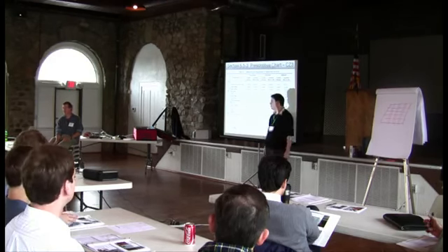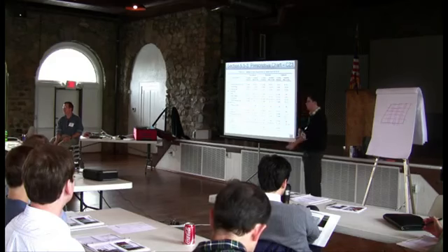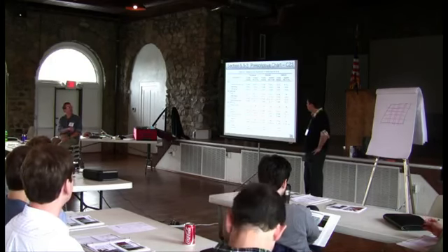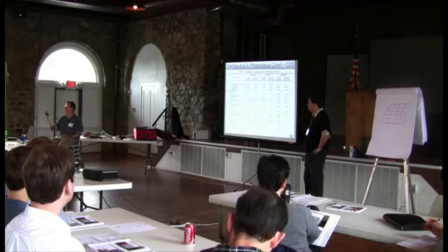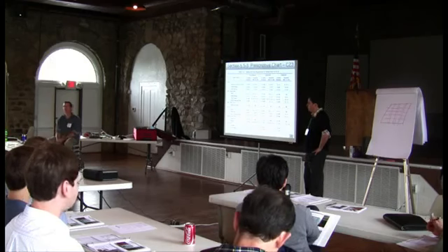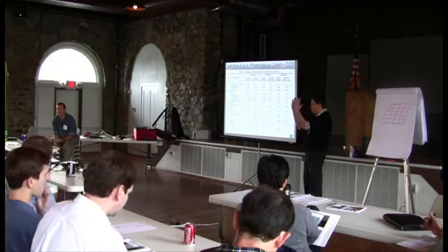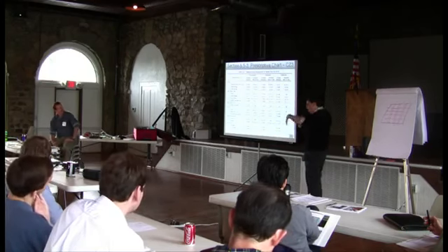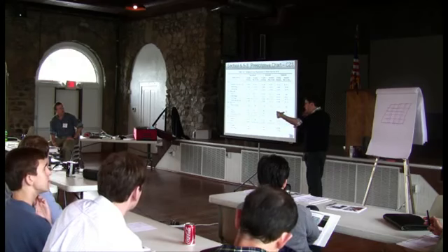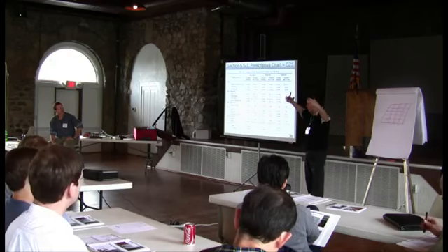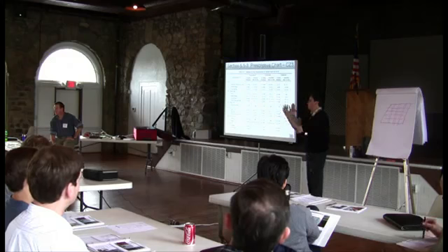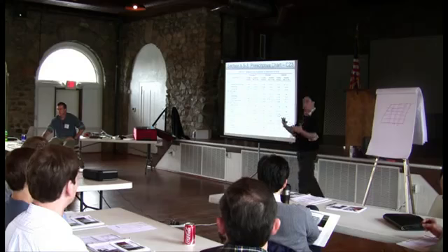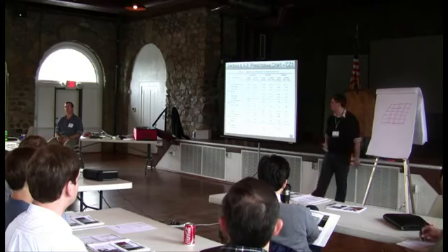Does that make sense, what Brandon just said? And that's an R13, and the other value is the sheathing. Correct. Yeah, the R3.8 is the insulated sheathing. It says continuous insulation is what the CI stands for, right? So you had sort of that double wall type thing that we were talking about, metal building, stud wall, or you've just got the metal building and you're infilling in between your steel columns with that metal stud, and that's acting as your exterior wall. That's going to fall under that steel frame. So really two different conditions. You have to consider that. Did we answer your question?